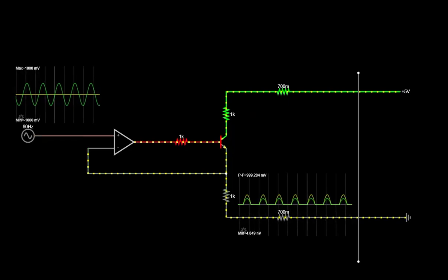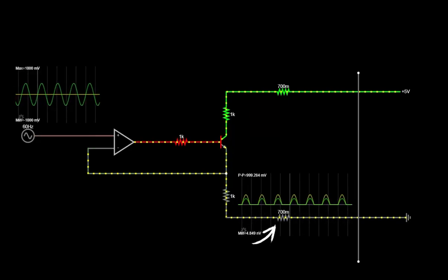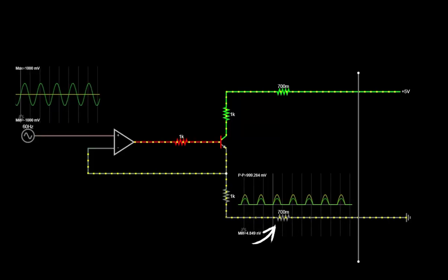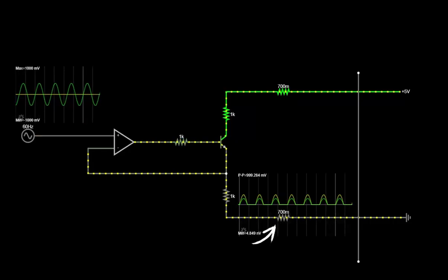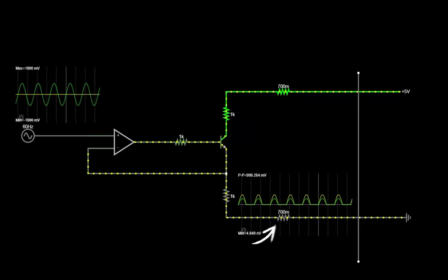The second issue being, because of the return end of the cable that goes to ground, that additionally has a voltage drop across it as well, which makes the voltage drop across the current resistor slightly smaller.